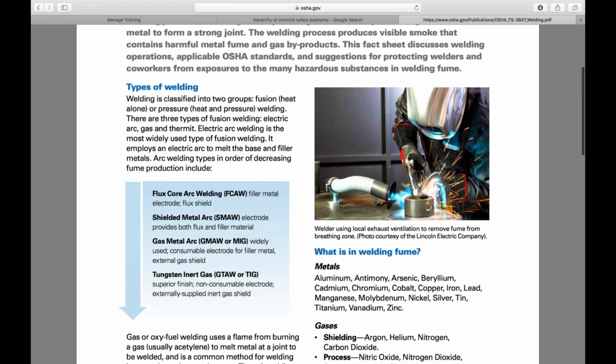If you roll over to page 6.4, we'll be talking about the site location and the layout, like we talked about. We want to figure out where we are going to be, and what site location and layout we are going to be in. We want to see what kind of traffic patterns. Is this on a highly trafficked road? Are there a lot of moving vehicles, either roadworthy vehicles or non-roadworthy construction vehicles that employees may be exposed to? Are there a lot of cranes, scaffolds, tractors, backhoes, street graders, just different types of equipment that they may be exposed to?